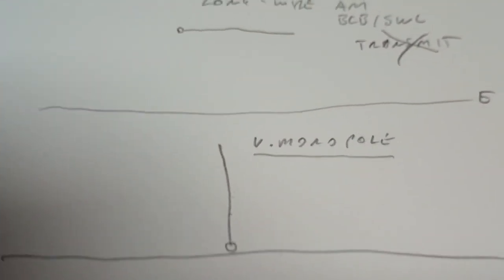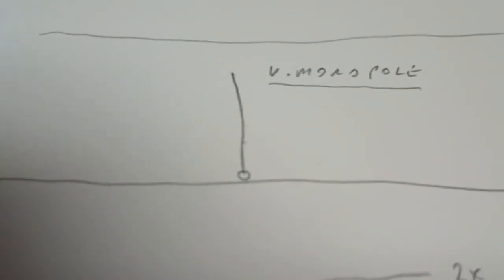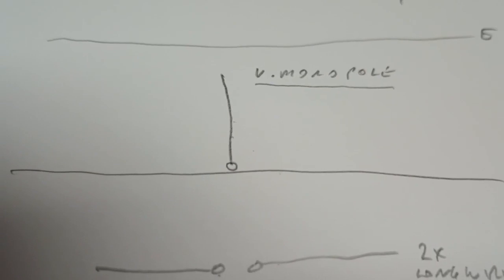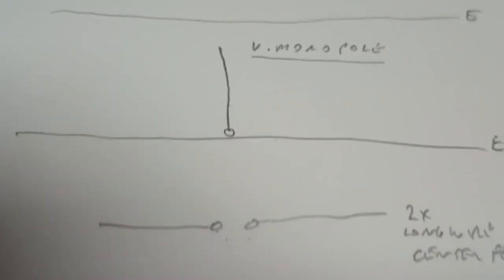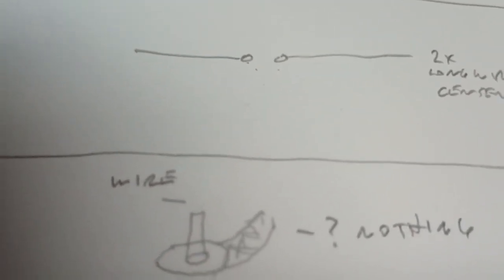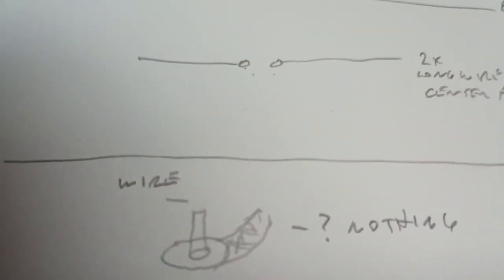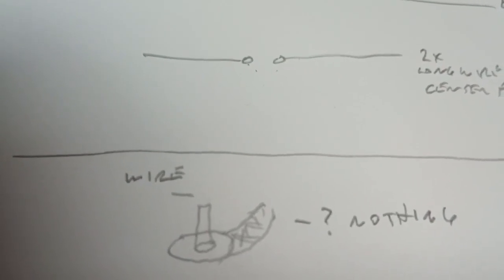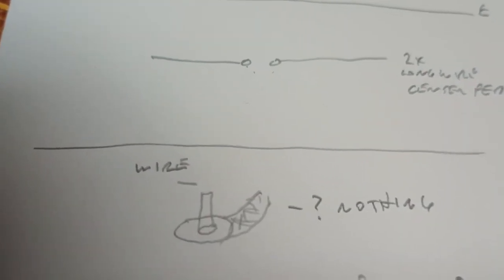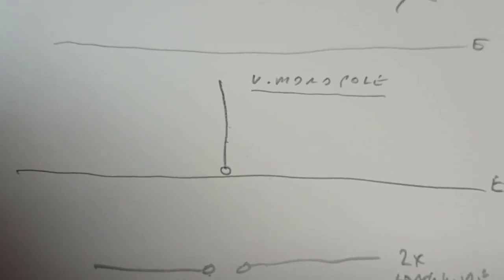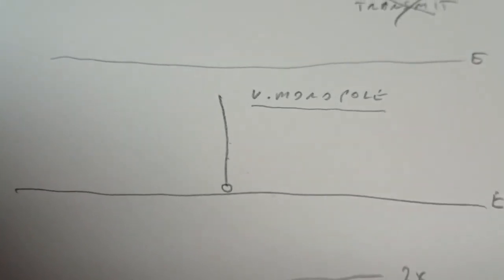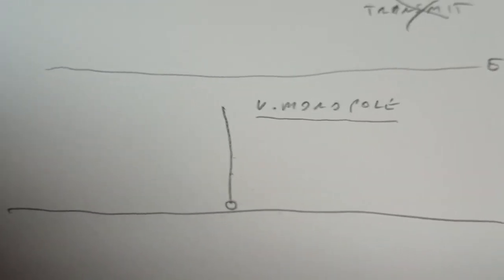That's not the case here. But it is the case here, and it is the case there. Only one connection. So the traditional basic answer for vertical monopoles in the ARRL handbook is to put a ground stake in the ground and connect what? We can't put the shield up where we're sitting. That would be uncomfortable and wouldn't work, so we ground the shield, and we violate the electrical code, because that's now grounding the chassis of the radio, and that's illegal. But in theory, that does make a 50 ohm feed point. That's what the old handbooks say, and it may work.